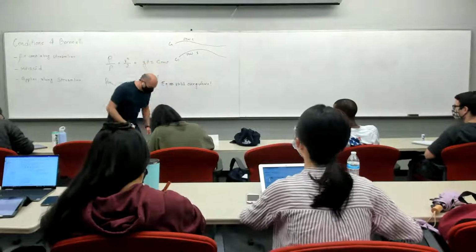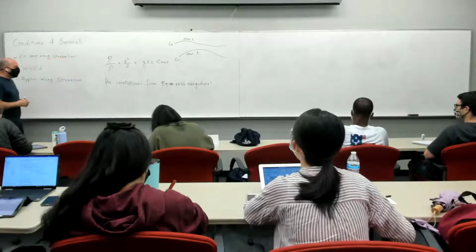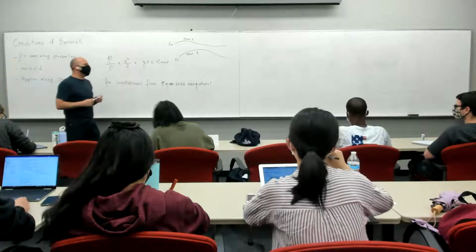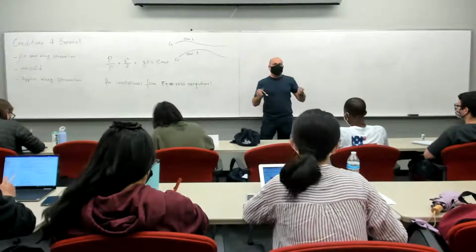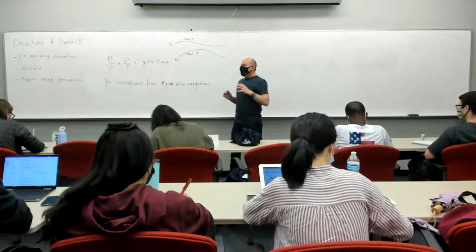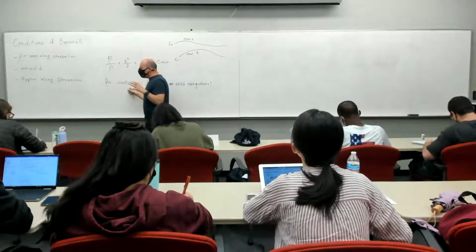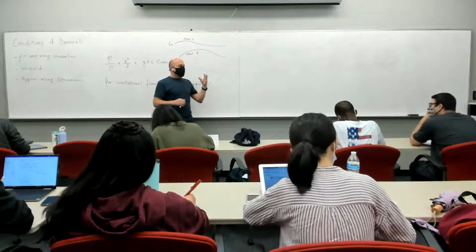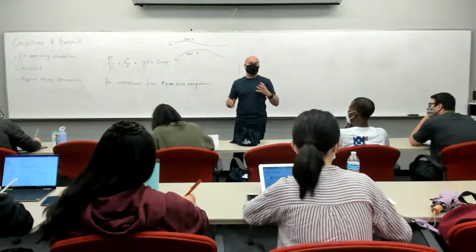Okay? We'll do a couple of examples now to see how it applies. Hayden pointed something out to me last Friday, which was interesting. So I know we have not talked about viscous flows yet and the viscous stress tensor. But it turns out that if you assume irrotational flow, okay, then the viscous stress tensor actually becomes 0.